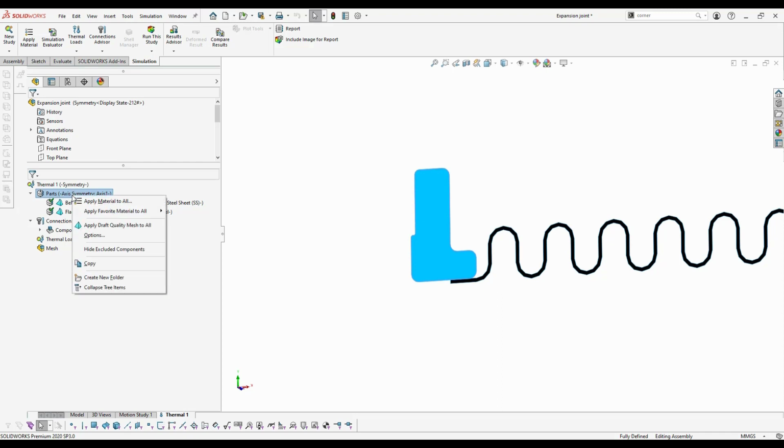If you want to add a material here, the point is that you're not applying that material back to the CAD model. So you're not changing any materials for your production prints. This allows you to take advantage of not only analyzing the parts or the files with what you've specified, but what if it doesn't meet your criteria, or you want to check out some different options for cost reasons? You can change the material here in your simulation tree without affecting your model or your drawing. So I just wanted to point that out.